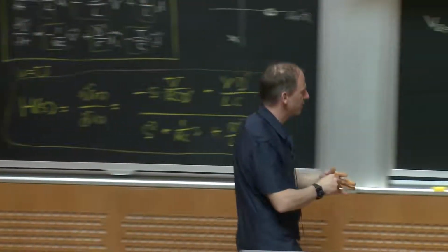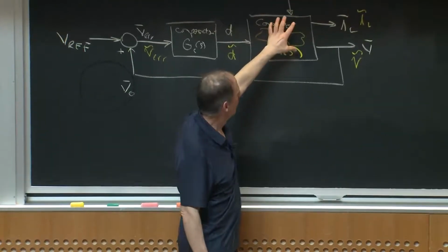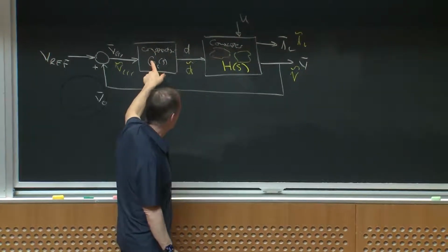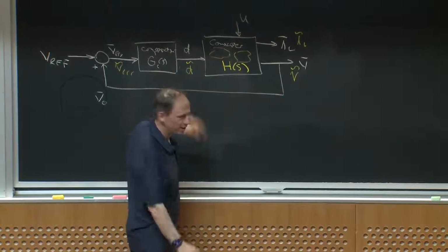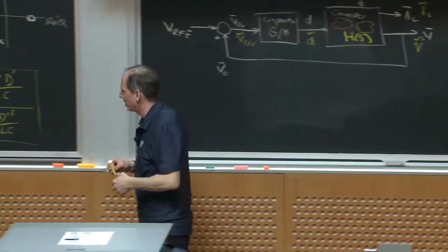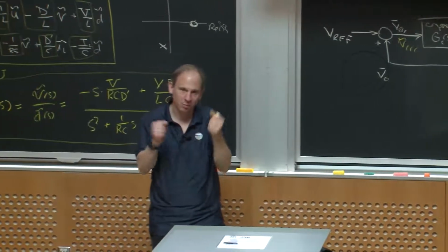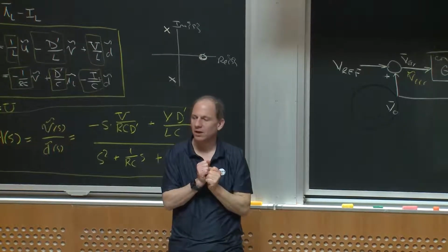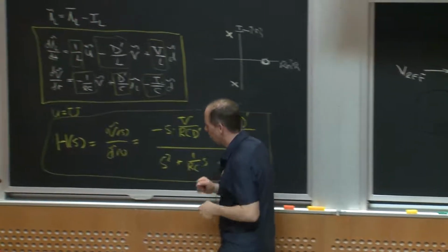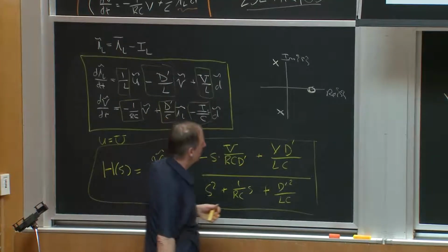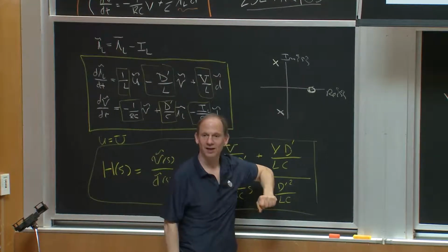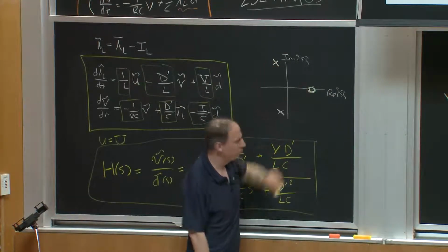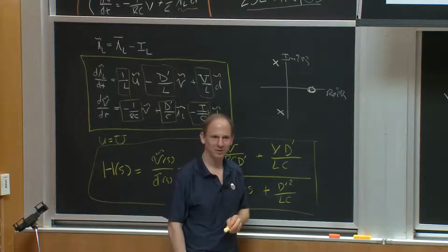Because usually if I take some system and I put some gain, forget about what this control is, so say it's just a proportional gain, and I close the loop and turn up the gain, what tends to happen is the poles move, right? The idea is I had some open loop poles, and when I put a feedback loop around them, the dynamics are going to change. And what happens is that the closed loop poles are somewhere else, okay? But it tends to be that as I turn up the gain, the open loop poles tend to move towards the open loop 0, okay?